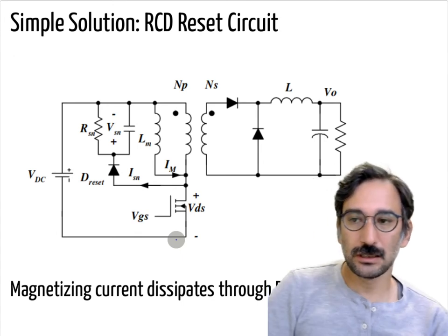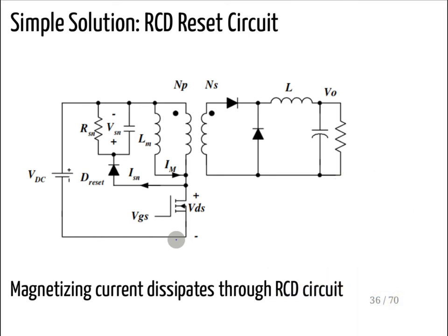In the first semester we talked about snubber circuits, and RCD circuits are one type of snubber. So here you see this forward converter with added LM. Once you charge it, so that one is being charged, and you are sending power to the secondary. But once that one is off, instead of destroying that MOSFET, now it has some path to discharge.